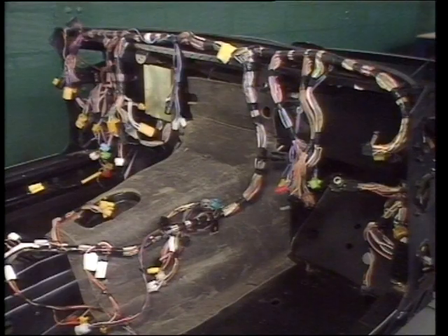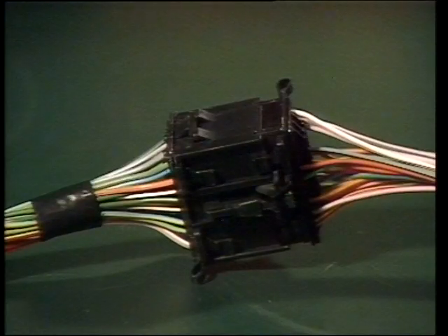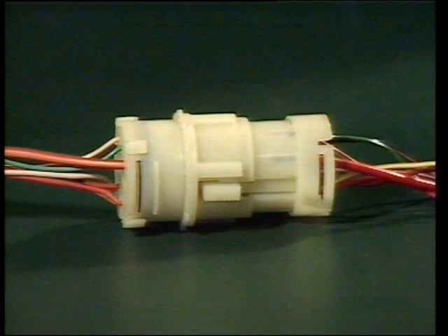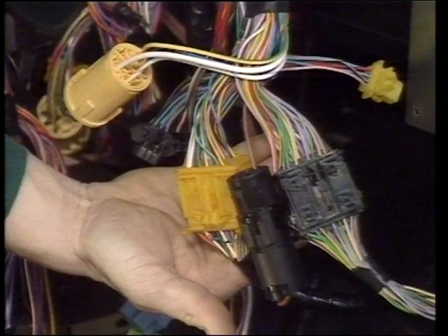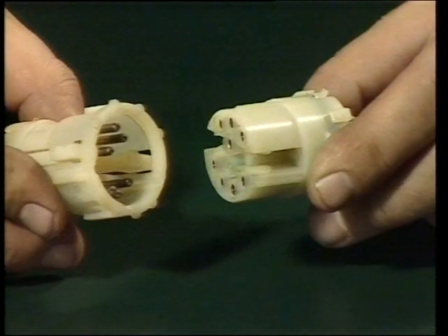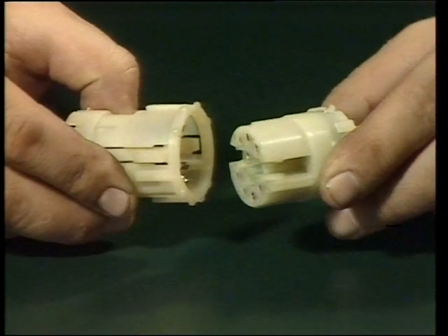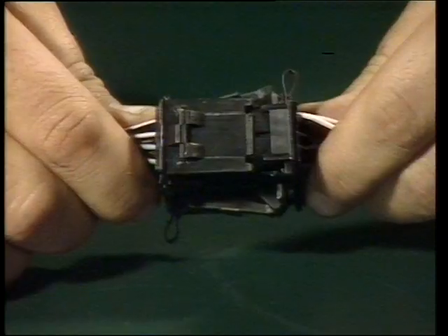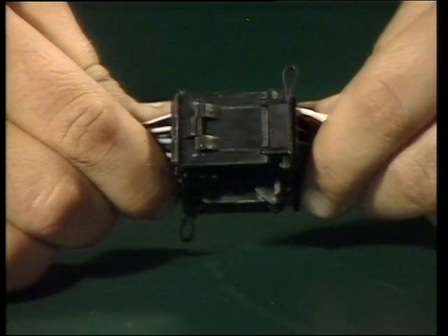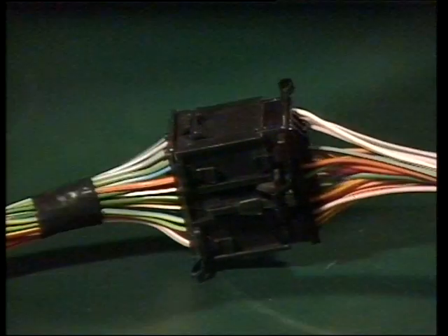Both side harnesses are joined together via the bulkhead harness by these connectors. The square connectors are used for signals. They're positive mate high density types, PMHDs, and the round connectors are used for power. They're positive mate Mark IV types, PM4s. In general, these types of connectors are used wherever a join in the harness is required. Both these types of connectors are male-female linked. This is the male half, and this is the female half. When joining them together, always ensure that the ramp lock mechanism is firmly in place.